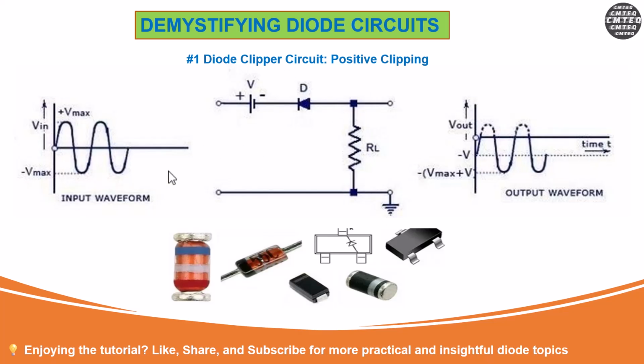So you have the input waveform, a sinusoidal waveform, applied on the input, and when the input voltage exceeds the clipping level that is set by this voltage source here, the diode becomes forward biased and starts to conduct. As a result, the excess voltage is clipped. That is what you're seeing on the output there, preventing the output voltage from going higher than the clipping level. So that's in a nutshell how the circuit operates.